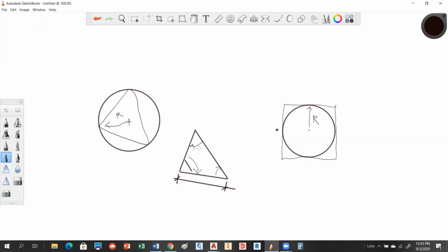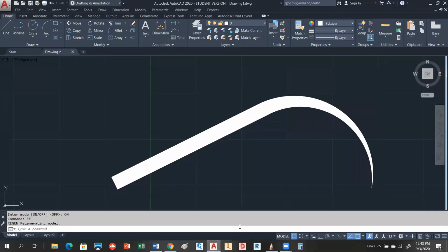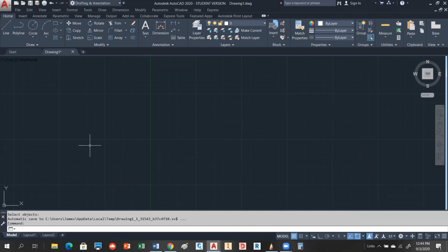The other thing about polygons is they are 2D closed polylines. So you're actually generating a 2-dimensional closed polyline. If you have your screen set up like I do here, let's go ahead and just erase everything. Type in erase and then the word all, and then hit enter twice. And you might want to do a zoom, enter, all, enter, just to get everything out. All right, so the polygon command is right here.